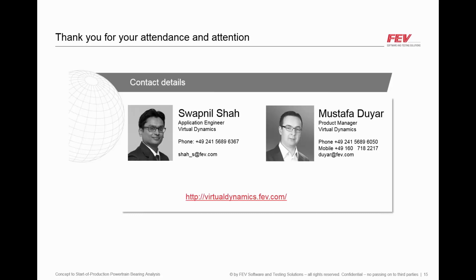Thanks, Swapnil. The next question is, if it is a friction model, can I really use the model to minimize the slipping? This is just in continuation with the previous answer. That is our aim. The clutch model considers the relative velocities, inertias, the static as well as the Coulomb friction, the Stribeck effects to model the clutch behavior. So you can, of course, use it.